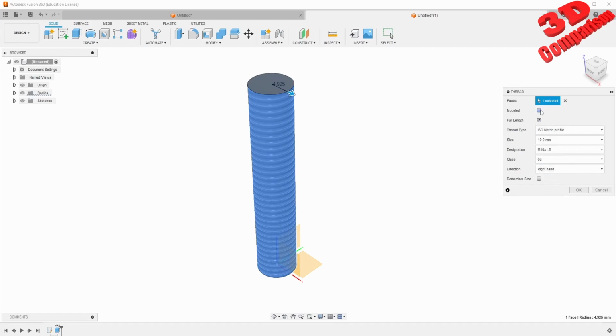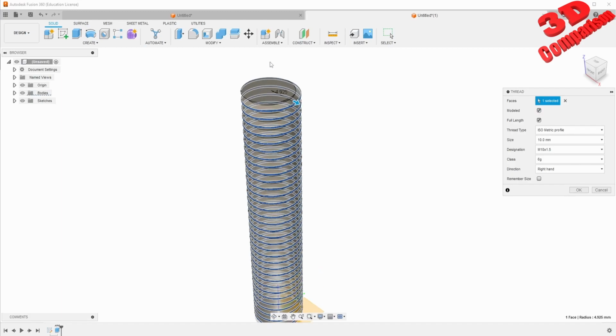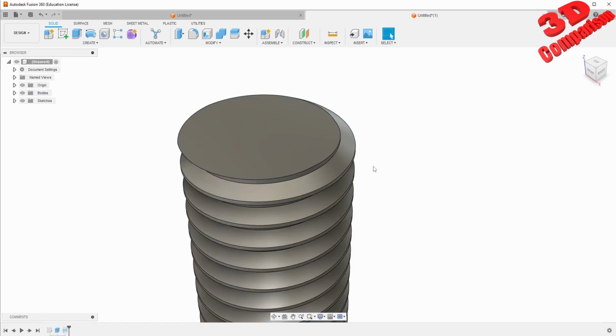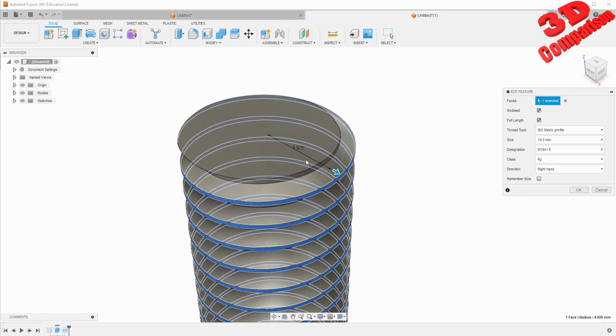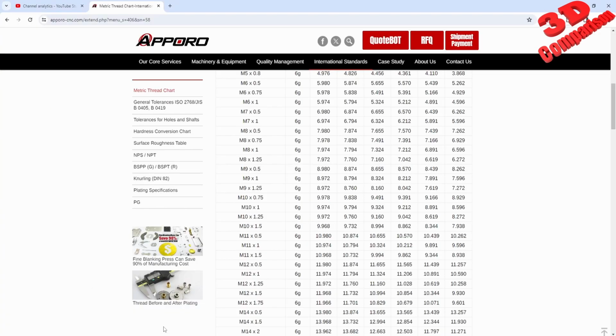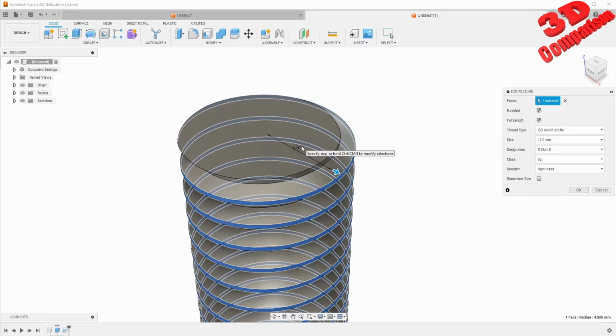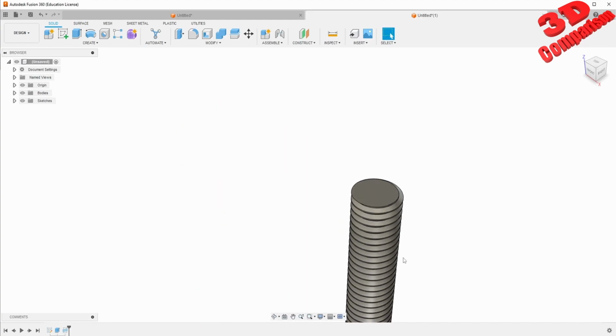And I just have to click on model. And as you can see, Fusion will automatically resize the element for us. Because we have the radius over here, which is 4.925. This will be the average value between maximum and minimum over here. So these two values divided by 2 will go directly on the value added by Fusion over here. So this is all that you have to do in Fusion.